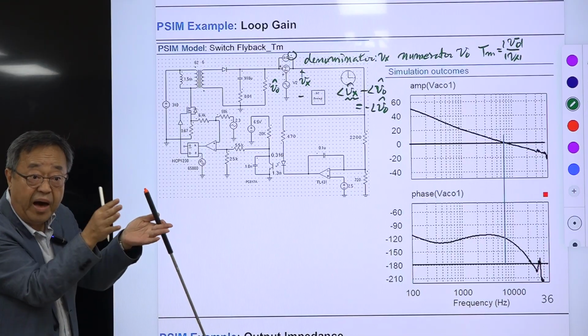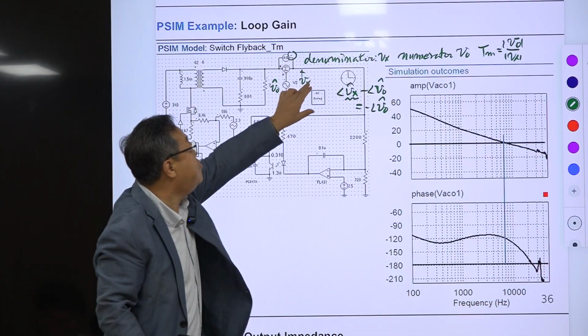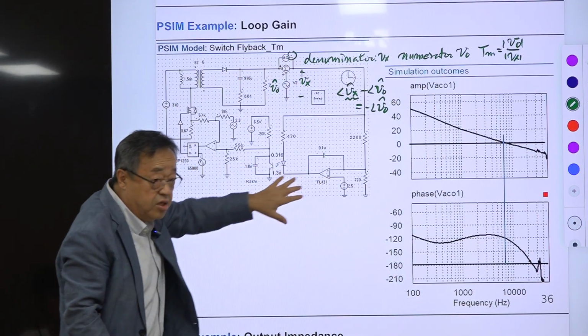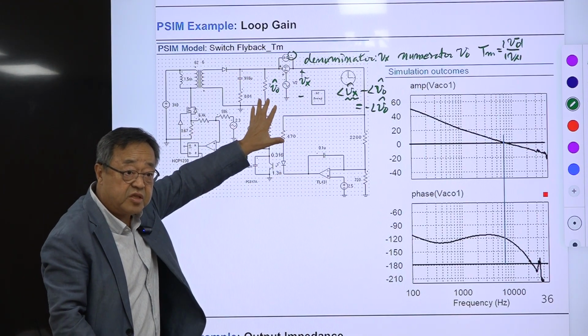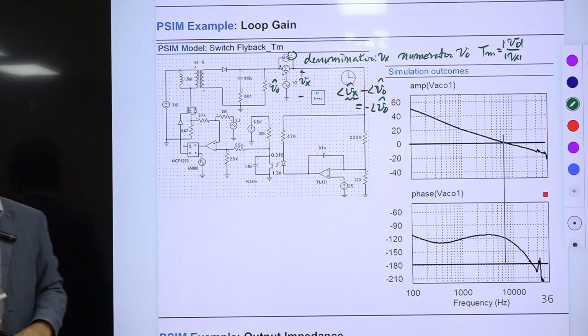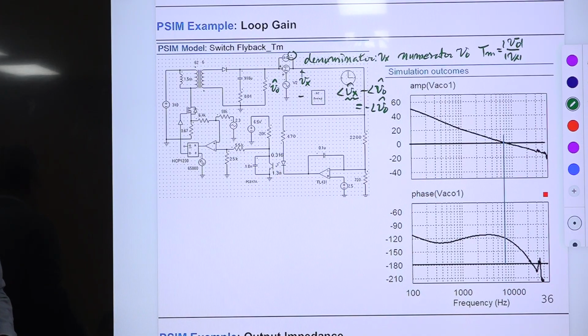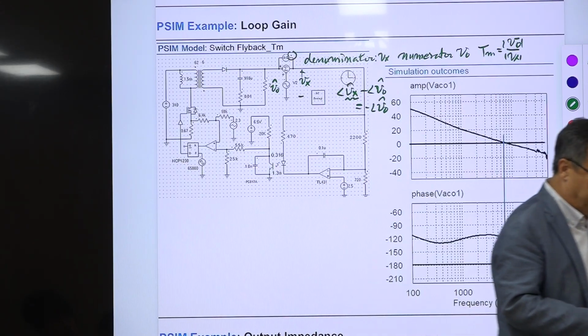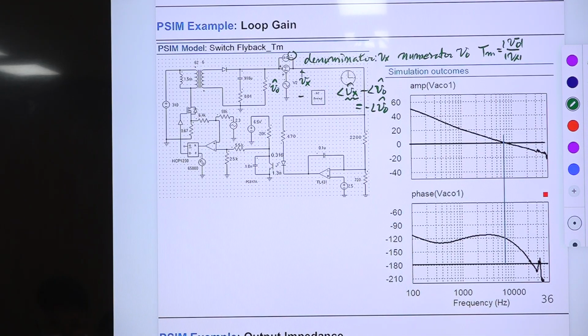The two of them combined generate an output sinusoid with exactly the same phase as the input injection signal, and then you just compare the magnitude curve. You can judge the stability of the system. Okay, that is the basic fundamentals about phase margin, gain margin, and stability evaluation using the Bode plot of the loop gain. That is the essential summary of everything.